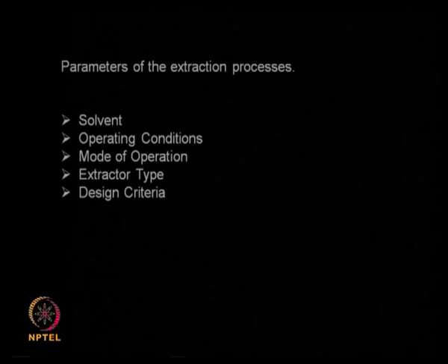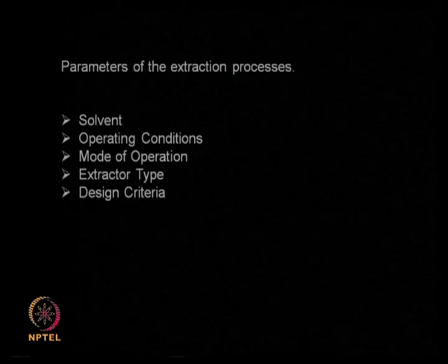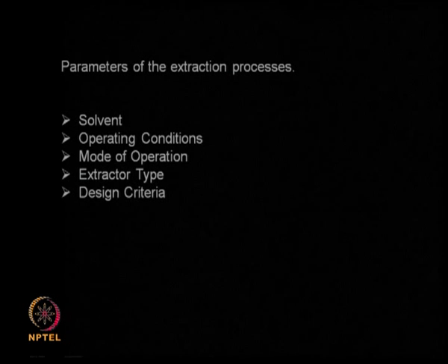Do I use mass balance, do I use steady state mass balance relationships, or do I use unsteady state mass balance relationships? Do I assume the extraction efficiency or the partition coefficient value to change from stage to stage? So all these criteria need to be considered when you select a design methodology. So all these are the parameters you need to keep in mind when you are designing a liquid extraction system.